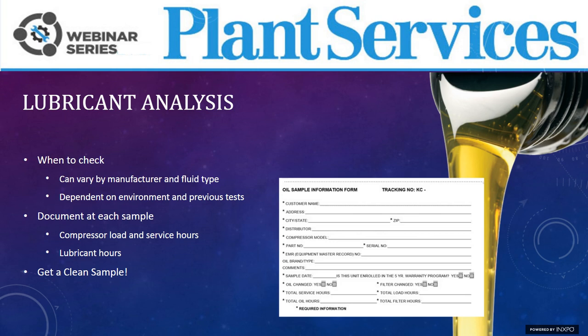All manufacturers provide a recommendation for frequency of oil analysis. Be aware that standard recommendations are not necessarily what the plant should adopt. And like we've mentioned before, if you have a dirty, dusty, high-temperature environment, then more frequent oil sampling would be recommended. Also, the type of lubricant, such as mineral oil or food-grade oil, will play a role.